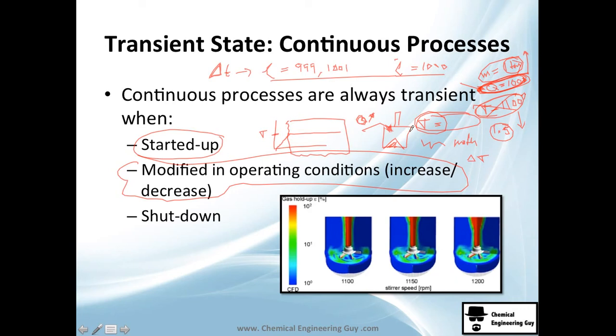You're going to increase it because you just increased the mass flow. So in this moment, the time you start, of course there's going to be a plan. You're not just going to drop everything like, okay, just increase the flow and add Q. No, we're not going to do that. They probably are going to do it step by step. They're going to increase a little bit, maybe 100 kilos, and they're going to use Q. They're going to let it stabilize for some hours, and then they increase another 100 kilos, and then they start increasing fuel consumption, and then we wait for the stabilization, and so on until you get to this quantity, guys.